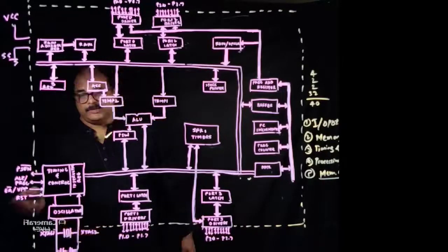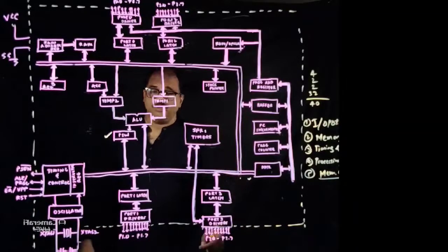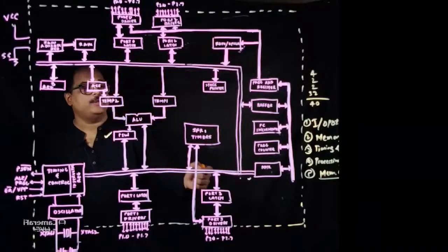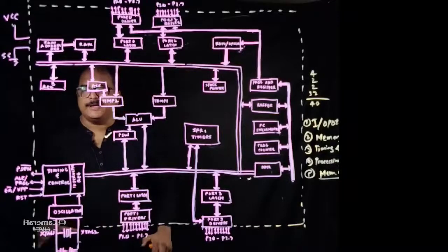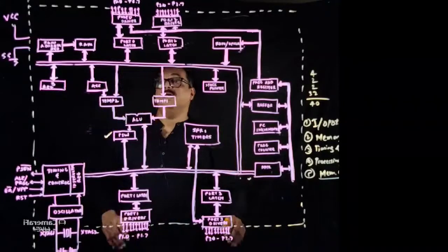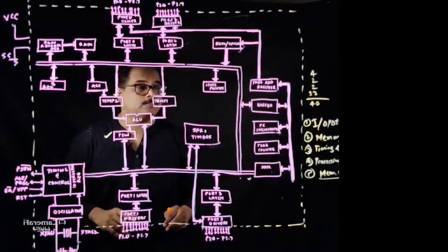You need to connect a resetting circuitry to the microcontroller so that whenever power is on, a power-on reset signal is generated, and accordingly the default values of the registers are loaded inside the 8051, and then the function starts. Okay, now at the last we will come to the middle portion, which is actually the